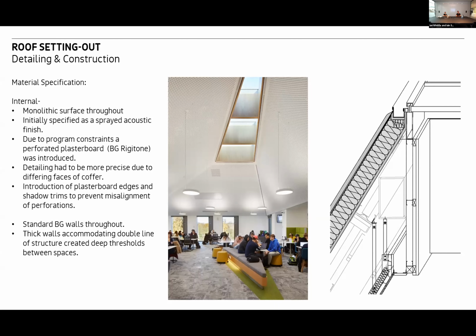The detailing had to be more precise. Shadow gaps had to be introduced. Edges on the plasterboard trims had to be introduced, just to allow us to get it to look as monolithic as we possibly could, but still staying within the original design intent.